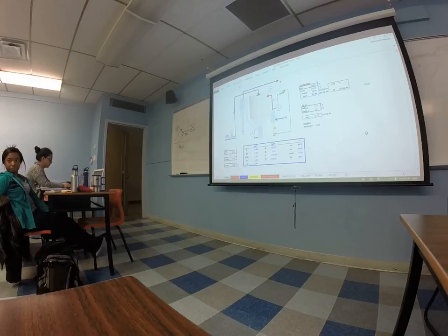And everyone knows how to calculate the solids in the milk stream? Usually, what percentage of solids did everybody have? Yeah. Let's say 20? So let's put 20% there. And most people operated at 210, although some groups I know operated differently, but let's say 210. And does anybody remember a typical dry bulb, wet bulb combination of the air of the room? 23 and 12, that's a good one.